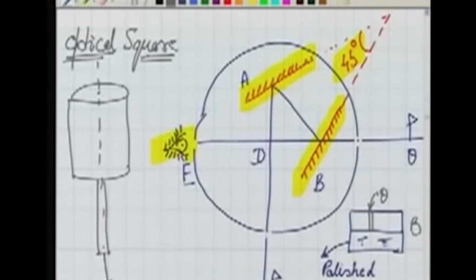Also, if there is another ranging rod at 90 degrees from this line EQ at R, what will happen? The rays from this R travel through this slit, pass and reflect from mirror A. They travel like this, they reflect, and again they reflect from the bottom part, which is the polished mirror part, and then they go to my eyes. So in this mirror, when I am seeing through E, I see Q as well as another image.